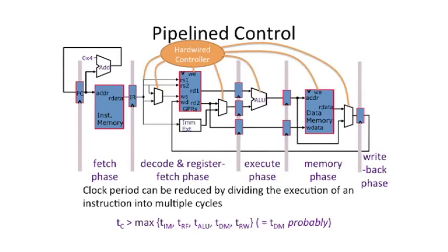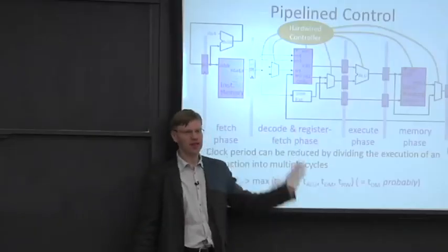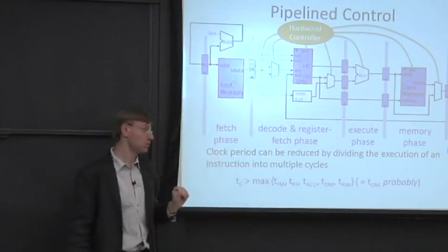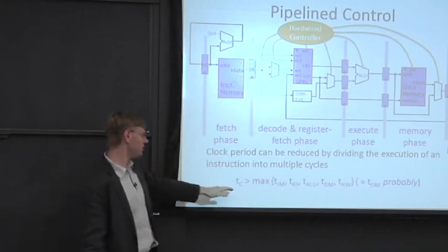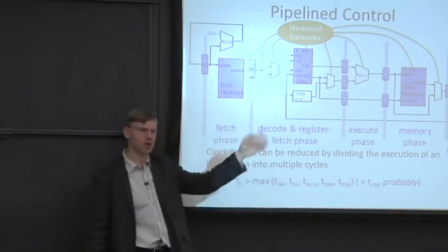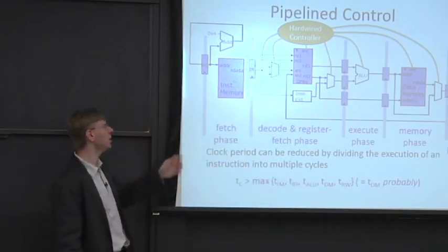One of the problems here, when you start to look at this, is, well, actually, before we do that, let's first look at how to use this processor in a multi-cycle yet pipelined fashion. So what do I mean by that? Well, let's say we're going to use the same data path and use the exact same control unit we had in the unpipelined MIPS processor. And in this design, the cycle time is now, let's say, close to 1/5 of the cycle time we had before, because we had 5 pipeline stages. So our processor executes faster.